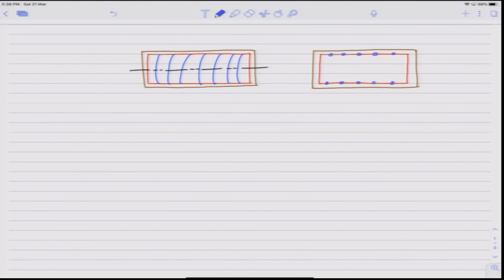Then they diffusion annealed this assembly at a higher temperature isothermally for different times, and after various time intervals they observed the distance between these two markers, and what they found, as the diffusion time progressed, the distance between the two markers kept reducing. That means the markers moved from the initial interface into the brass side.